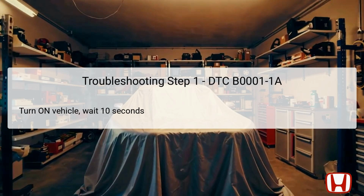This simple step is crucial, as it establishes the foundation for further diagnostic work by confirming that the system operates as expected initially. In the second troubleshooting step, the driver's airbag is inspected. Before any disconnection occurs, you must follow the 12-volt battery terminal disconnection procedure to ensure safety, as the airbag systems are sensitive to current changes.